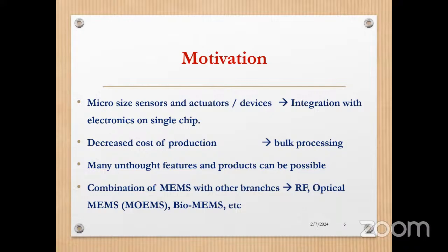The cost of fabricating a single antenna is equal to the cost of manufacturing, say, 1,000 antennas, or say 100 antennas. So if I produce a device fabricated using MEMS technology in low quantity, the cost of the component is going to be very high. So bulk fabrication is the only way these technologies can be widely implemented and used.